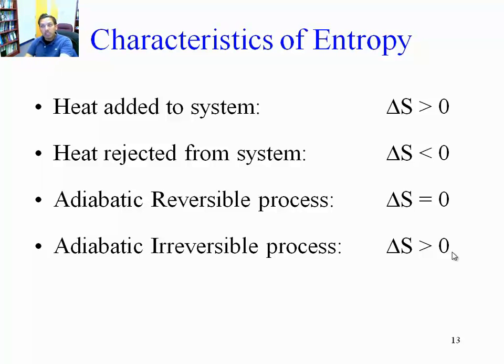If heat is rejected, the entropy is going to go down. Now, as I said, this entropy quantity or property has many repercussions and many implementations and interpretations. From the thermodynamic point of view, it's the strength of the irreversibilities that occur in the process. It's a measure of the efficacy of a system to absorb or to transform energy from heat to work or from work to heat.